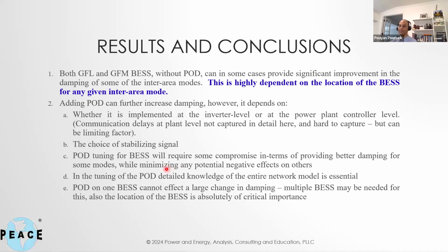The other thing was, POD tuning for the best, obviously it requires some level of compromise, because sometimes you would find that if your POD tuned best for a given inter-area mode, it might help some of the other inter-area modes, but then sometimes it might slightly degrade, or not degrade damping, but change the frequency of some of the local modes.